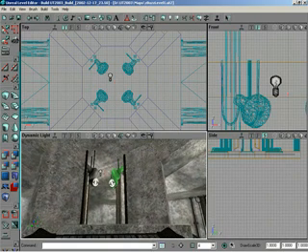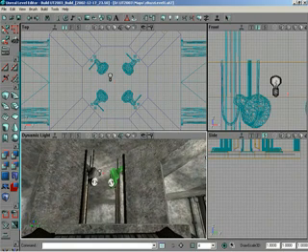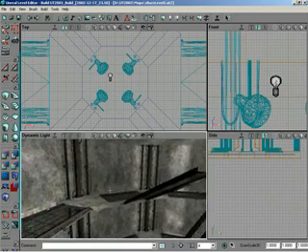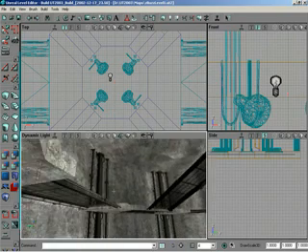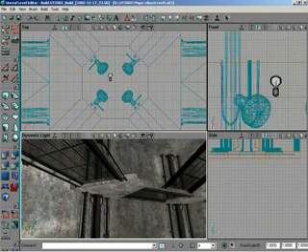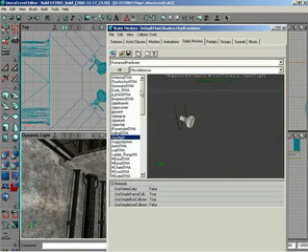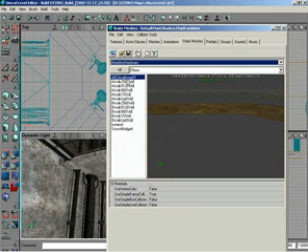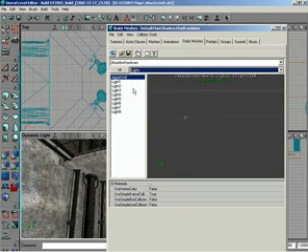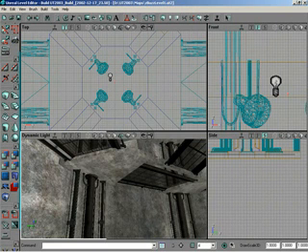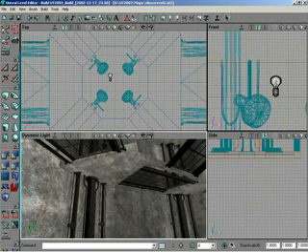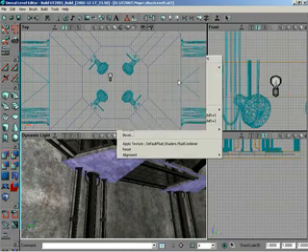Very cool. All right, so now you want to go ahead and start adding all of our actual light fixtures that are found all the way around the arena itself, the walkways. We're going to add lights underneath each of these little supports that stick out from the wall. So for those, we're going to go and grab, let's see, these are going to be the abandoned hardware. Let me see if I already had that open or not. And sure do. From there, we'll grab under lights, and it's going to be the A-Light 01AB.